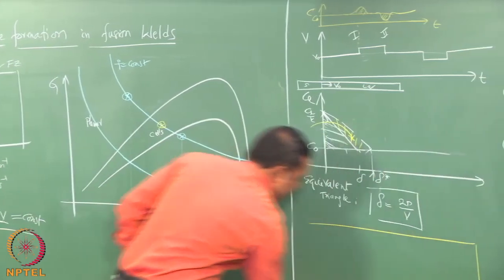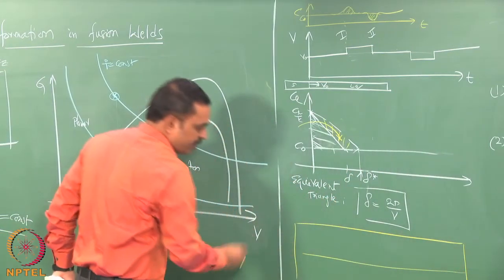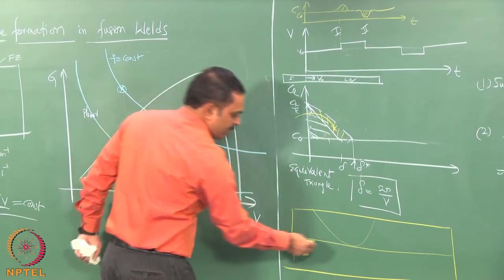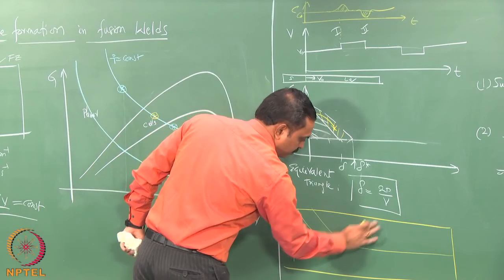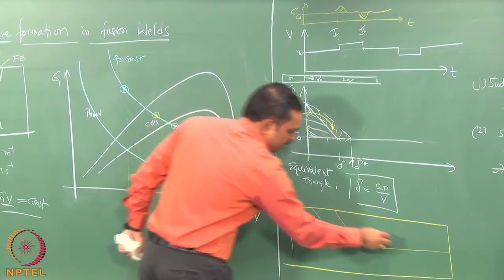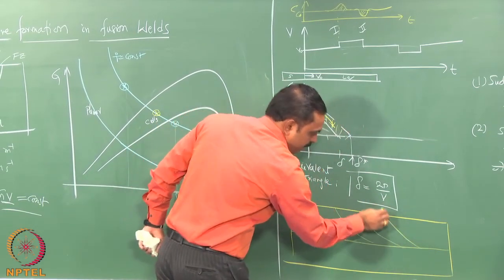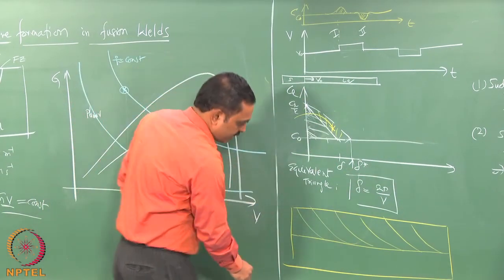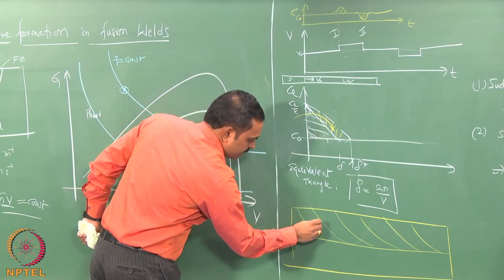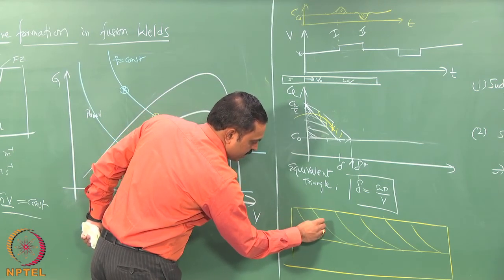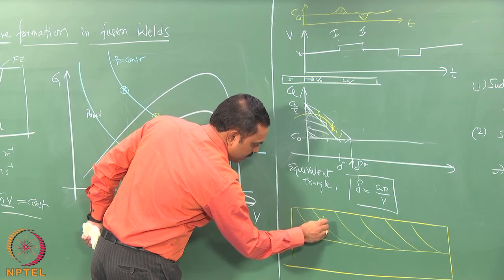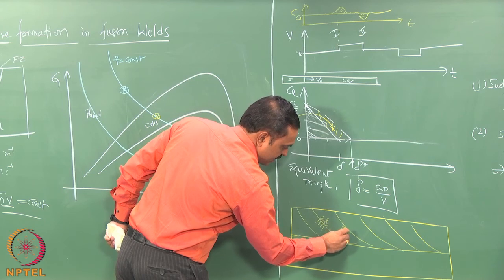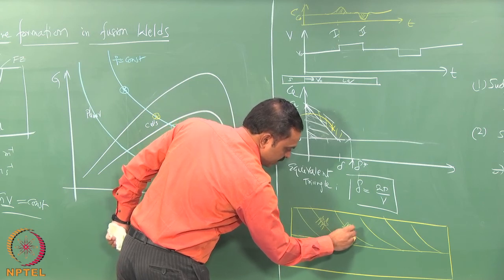And how does that manifest? It manifests in the longitudinal section as follows. This was the trace of the fusion zone, which means that at every disturbance you may have traces that come with microstructural changes or composition changes. So, when you etch a longitudinal section, you would see that, for example, cells that are supposed to grow may actually start becoming dendritic locally, or what was growing as dendritic may start growing as cells and vice versa.